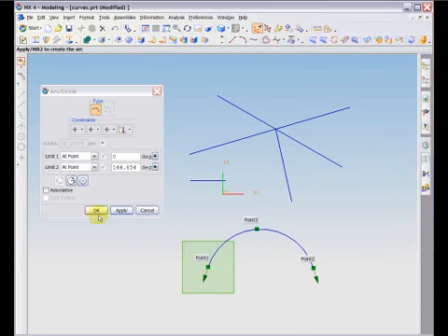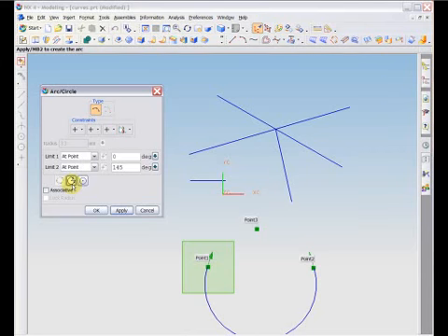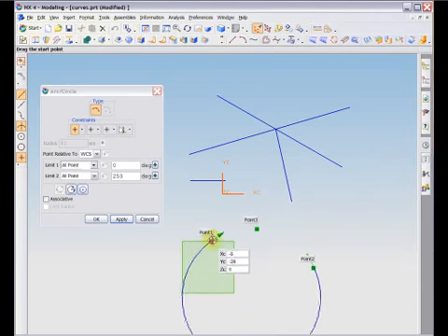One example is the Complementary Solutions option, which will return the complement of the displayed arc. Another option is to choose to make the arc a full circle. As in the line, you can also just grab the handles and drag the endpoints or radius with your mouse.